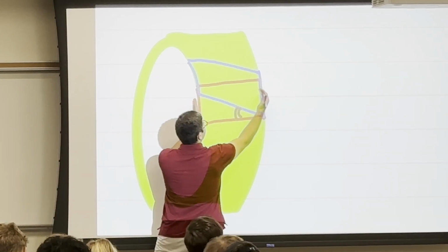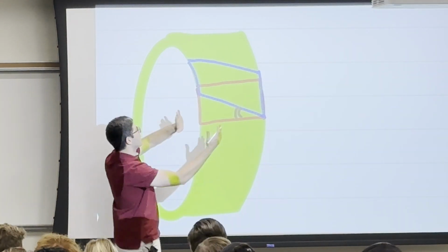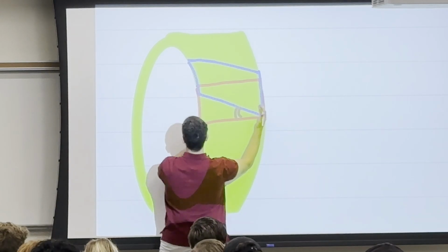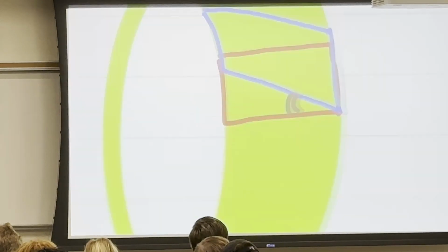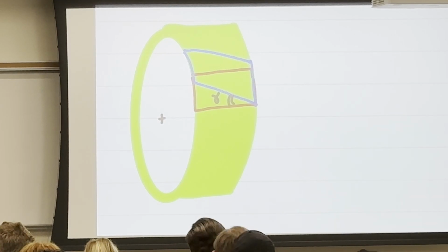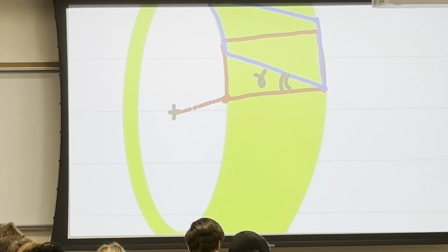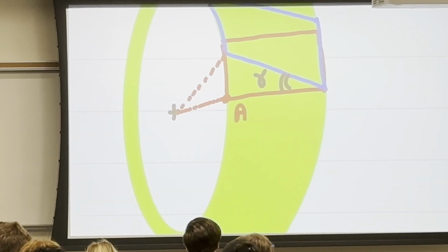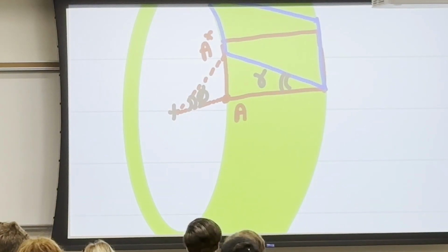If we have a plate that's like this, and we didn't apply any tension or compression to that plate, we just rotated it. And when we rotated it, we moved it that way, which is parallel to the cross section, we will end up having a gamma here. Okay? So now I do have a gamma, and let's say this is the cross section. And originally, we used to call this point A, and this is, for example, the A star. And from what we said earlier, from the cross-section level, this angle we call phi, which is the angle of twist. Okay?